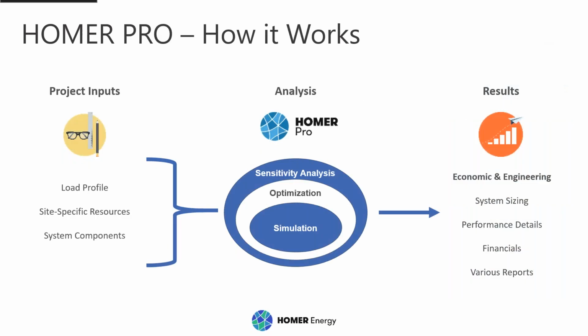So just briefly, how Homer works, and then we'll go into a model a little bit later and demonstrate the actual functionality of the software. You begin with a series of inputs in the software. You need the load profile. Again, how much energy is being consumed and when is it being consumed? Or you can even simulate that as well. If you don't know what the exact number is, you can create that yourself, and we have tools to help you do that.